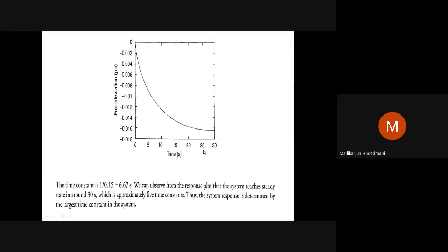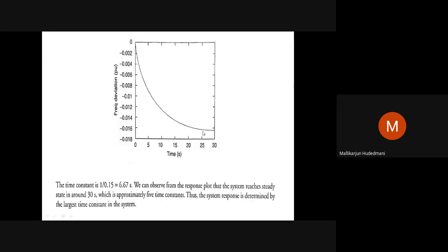Notice that whenever this system experiences a step change of 0.01 pu load, then this response, when I plot it with respect to time, becomes a variation, and this function is utilized. You can see here time and frequency deviation. This is a little extra work. Unless we have an experimental simulation, we cannot do it that easily. But this graph shows the response plotted as in the figure using this expression.